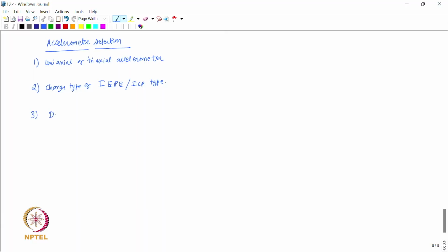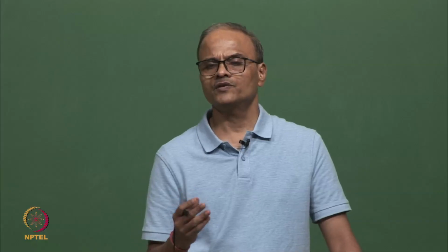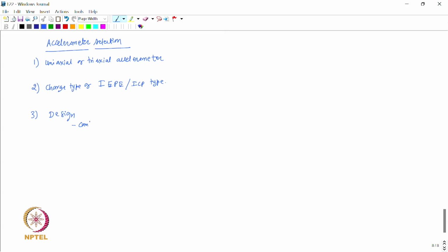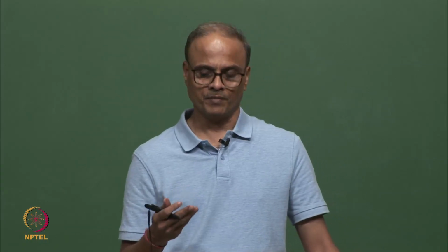Then the design. Design basically refers to how the piezoelectric crystal is arranged with respect to the seismic mass. There are several designs available like compression, then we have shear design, we have flexure design. So, let us look at compression and shear designs. In the compression design, the piezoelectric crystal or the disc is under compression.